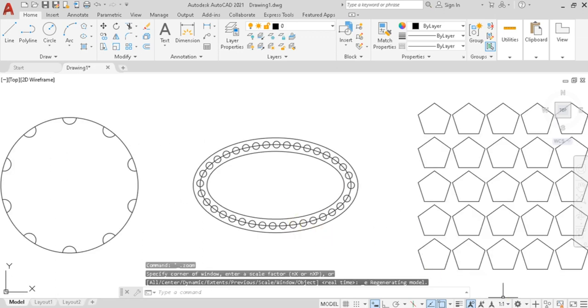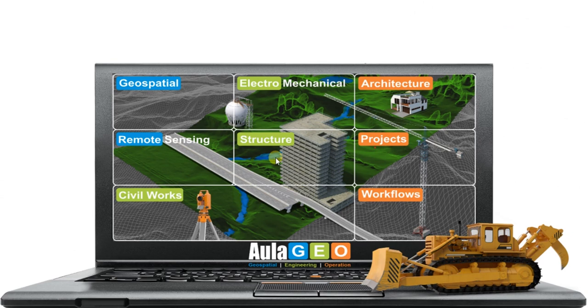So, here we can see all three arrays. This was all about the session of arrays, where we have learned how to create a polar array in case of circles and arcs. Then we have seen the path array for irregular shapes as well. And then there is rectangular array. Rectangular arrays are most commonly used to create patterns on different surfaces. The better you play with these features, the better you get, because there are different types and options that could be used to vary your arrays. So, practice them as it will make you perfect.